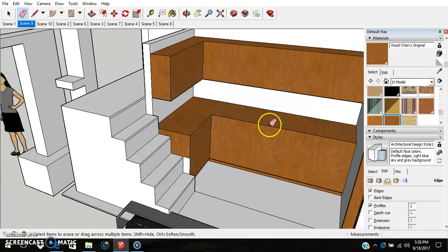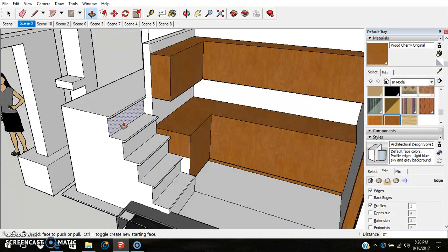I can deal with the kitchen later. And then what we'll do, so we have a little bit more surface area to step on, we can push this in 1.5 inches. And so we got the push-pull tool P, push that in 1.5. And then usually after you do that, if you're repeating that action, you can just double click where you want to, and usually it will copy that action.